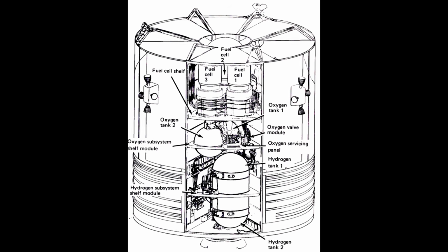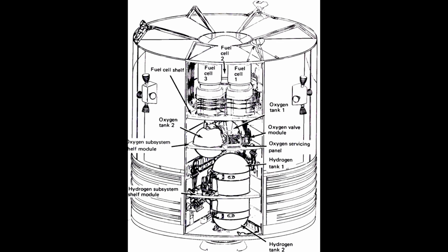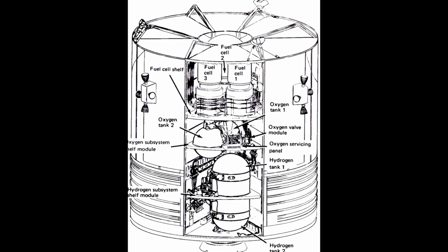Specifically, they looked at the propellant tanks that were used by the fuel cells, and they added an extra one. They removed the fans for the stirring and the thermostats, and in the command module, they also added a water tank, because one of the problems was that they were running low on water since they expected the fuel cells to be making that. So yeah, they never made any changes to that, but of course it all worked out in the end.